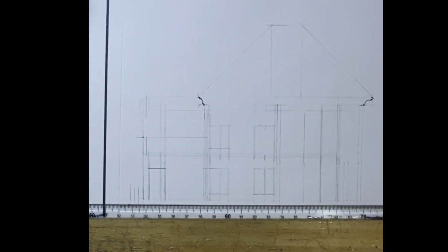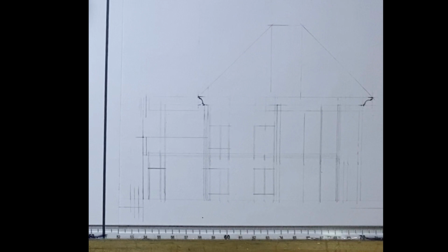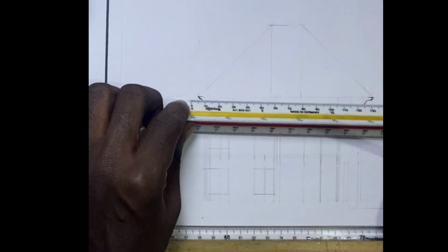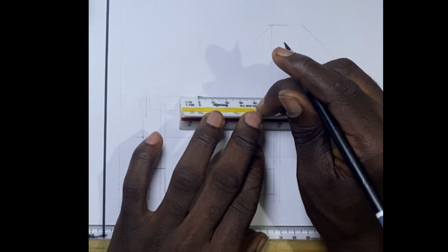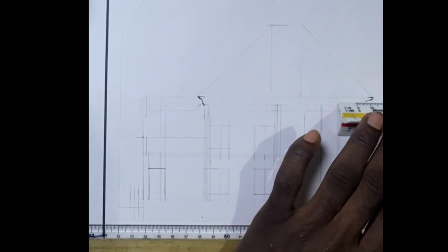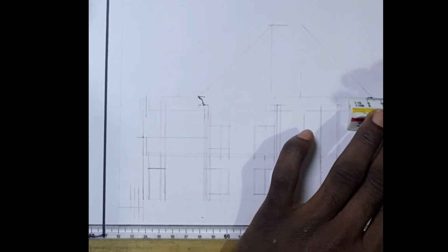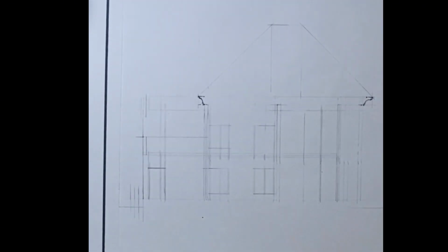Alright. The next thing to do is to connect this point to somewhere around there in order to show that the concrete fascia flushes into our wall. Yes, and for us to do that, take a measurement of 450 up here. Yes, 450 millimeter. Same thing here, 450 millimeter. Then we join the 2 points.